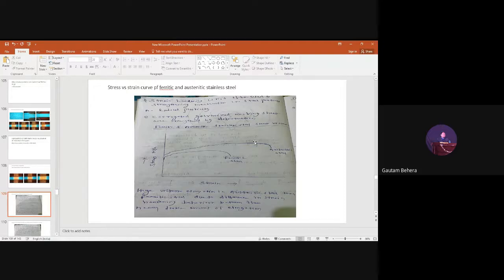So you can see this one shows more strain hardening effect here. And there is an interesting point. Strain hardening is not often used as a strengthening mechanism in all steel products, because it reduces the plasticity in the materials. That is the reason. Corrugated galvanized roofing sheets are strengthened by deformation. This is one of the examples where we give steel a strain hardening effect. You have seen this kind of sheet on the top of a roof.